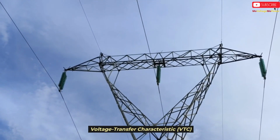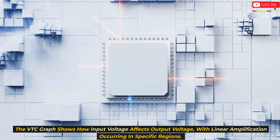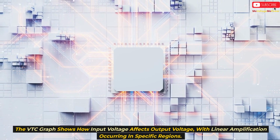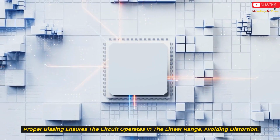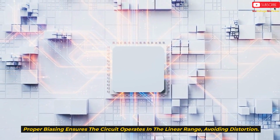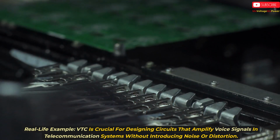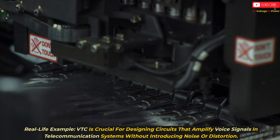Voltage transfer characteristic, VTC. The VTC graph shows how input voltage affects output voltage, with linear amplification occurring in specific regions. Proper biasing ensures the circuit operates in the linear range, avoiding distortion. Real-life example. VTC is crucial for designing circuits that amplify voice signals in telecommunication systems without introducing noise or distortion.